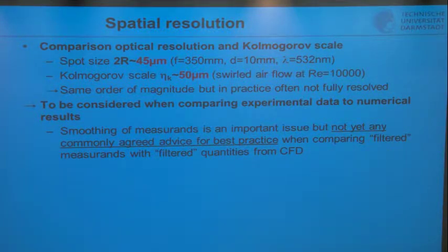For those of you doing, for example, large eddy simulation, you have a different kind of filtering. You're filtering your conservation equations, and because of the nonlinearities, it depends on the stage where you do the filtering. A similar way of filtering would be a fully resolved DNS. You resolve everything in the simulation and then apply the filter that you have from experiments.